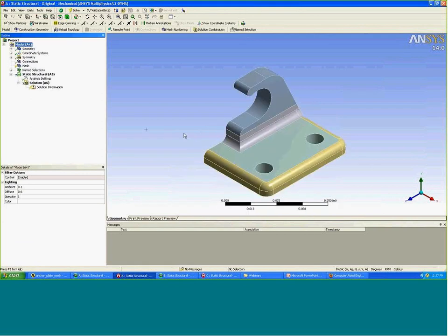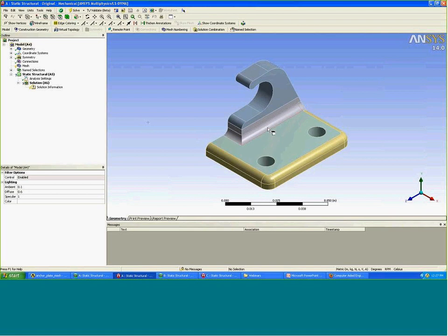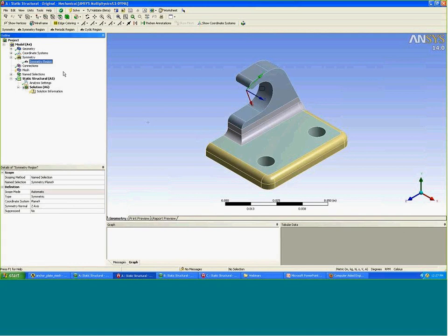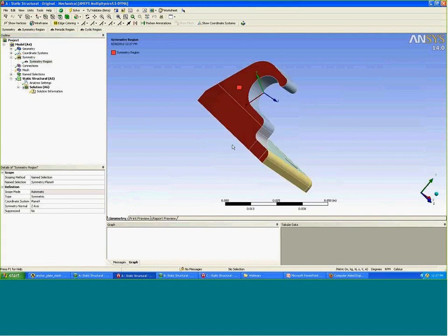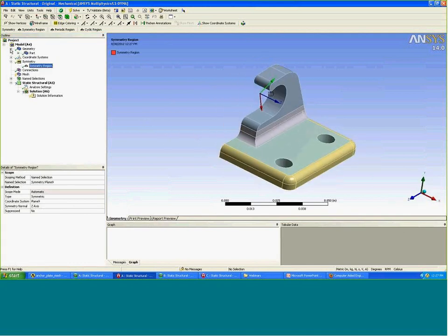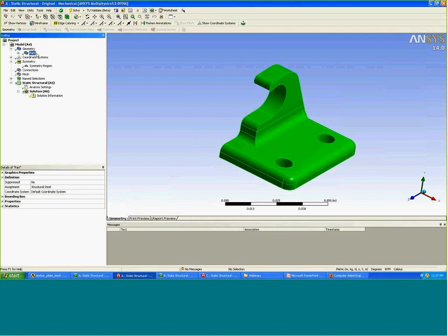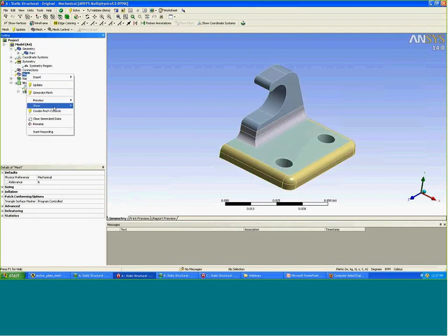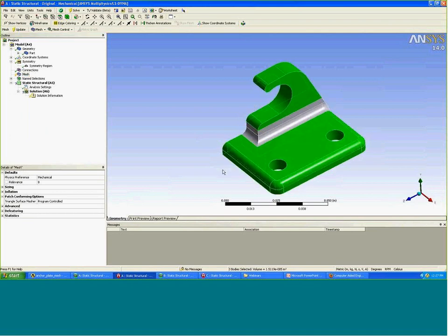You see that I have the symmetry meshing that I have in Designer. Now the symmetry conditions region here is where I used the symmetry tool. Symmetry shows I have a multi-body part, and click on meshing. It shows exactly what I thought when I was doing the slicing. I have 3 sweepable bodies.